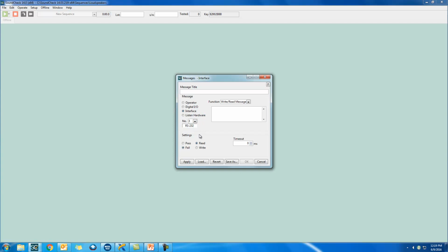Once each of them is selected, the other options in the step will change. Now if I click Digital I/O, you can see there's different port dropdowns. I configured it for 3 ports, which are all input, so whichever one of these I choose, there's 8-bit ports that are all set to input. If I write a sequence, I can simply insert a message step that will reference my different interfaces.